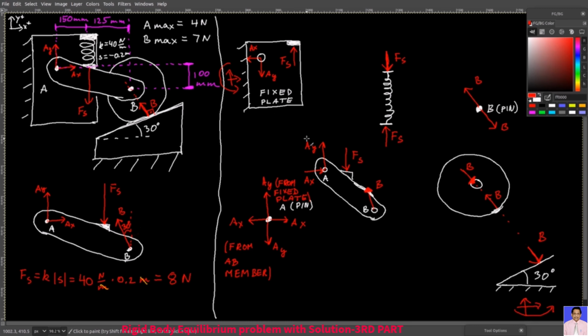Because of the fact that the mechanism is not moving, all the components, if you look at them separately, they will end up being in equilibrium. They have to be. If they are not, then they would start moving, which is impossible when nothing is moving. So when your structure consists of several members, like this one, and it's not moving, then you can disassemble this structure in your mind like this and apply Newton's third law.